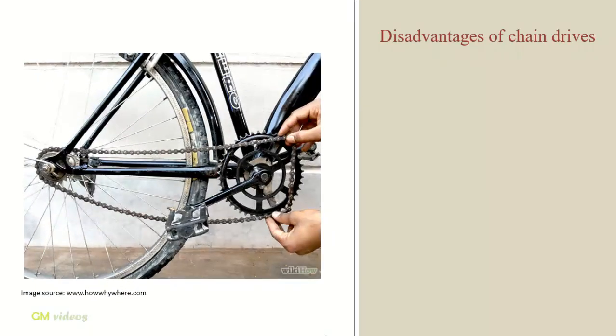Disadvantages of chain drives. Wear at joints increases chain pitch. This increases the chain length. Chain may therefore leave the sprocket if tension is not adjusted from time to time. Chain drive therefore needs accurate mounting and careful maintenance.